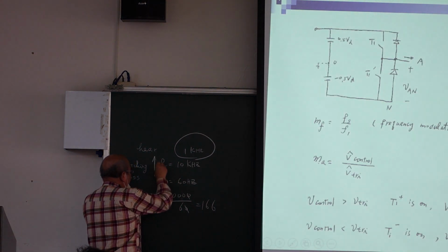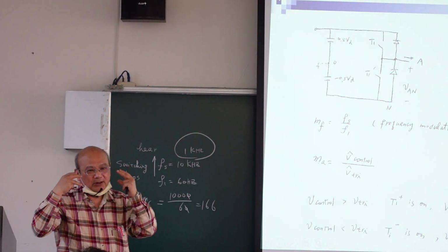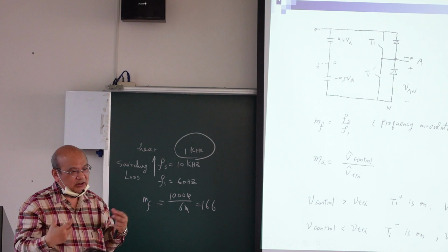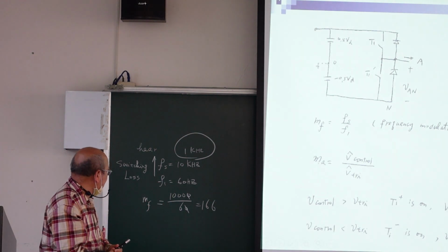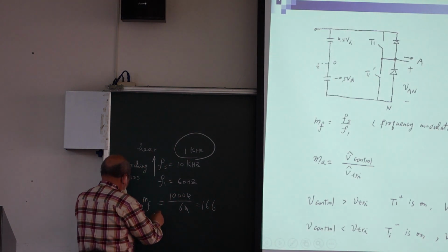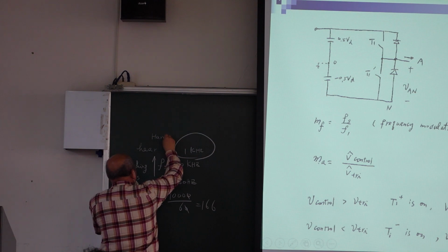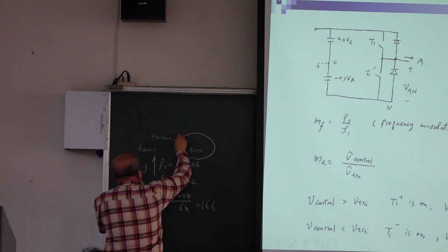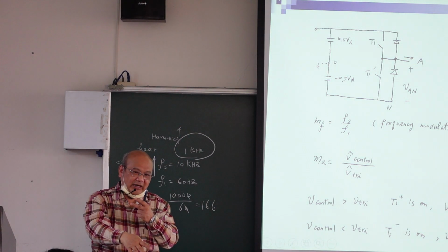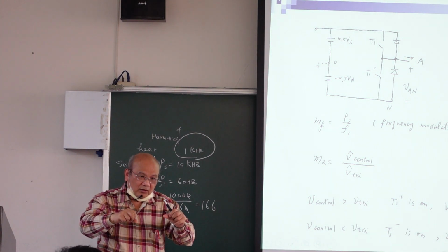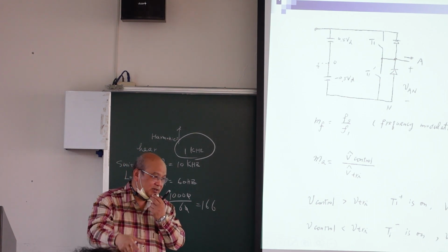We have to push to 10 kHz. Otherwise, your ear cannot endure. It creates noise. And what is the next problem? If you use 1 kHz, then your harmonics will increase. So higher carrier, smaller harmonics. So you have to push as high as possible.